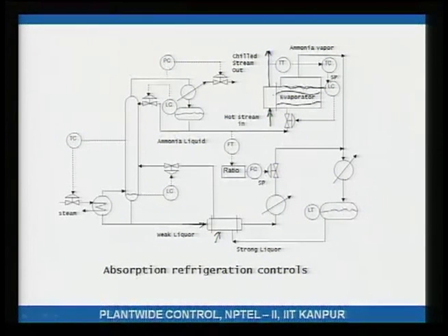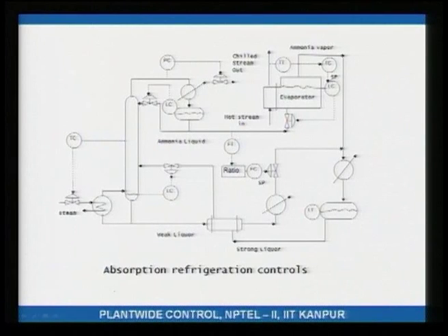So, this would be cold, for example, and not much heat will get transferred here. Why is that? Well, the liquid side heat transfer coefficient will be much higher than the vapor side heat transfer coefficient. So, the amount of heat transferred here will be major, and the amount of heat transferred here will be minor. The more the liquid level, the more the heat transfer rate. I hope this makes things reasonably clear.